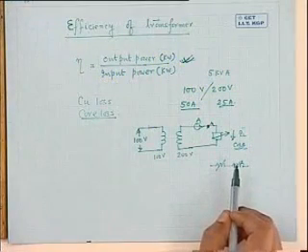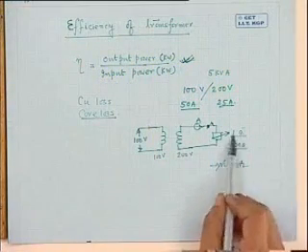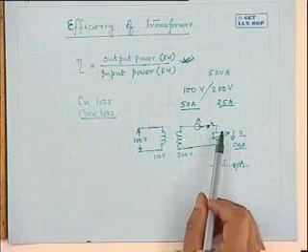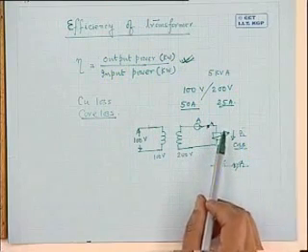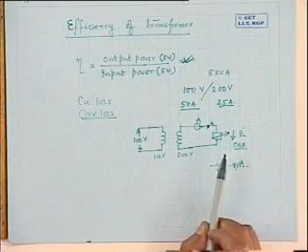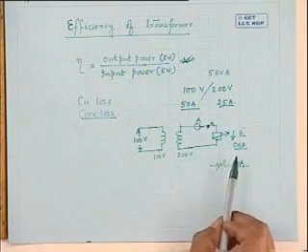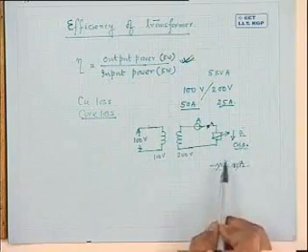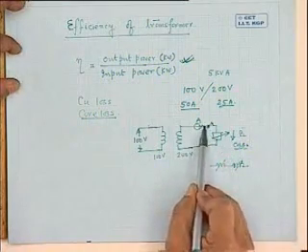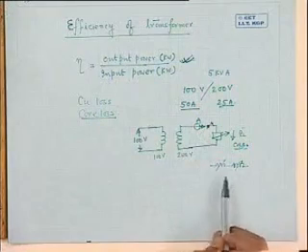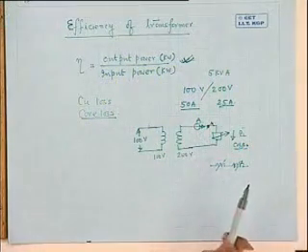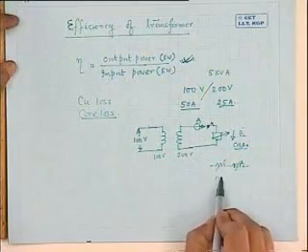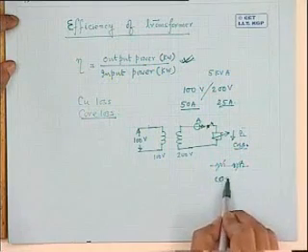That is, theta 2 is constant. But I am varying the magnitude of the impedance Z2, and I can load the transformer to 25 ampere. What I am trying to tell is that for a given power factor, I can pass rated current by manipulating Z2, definitely.